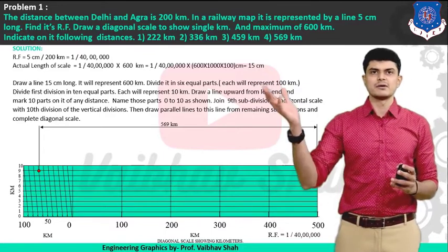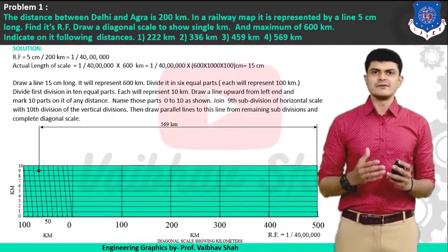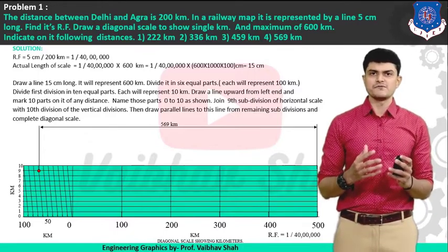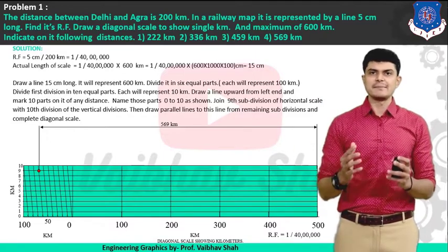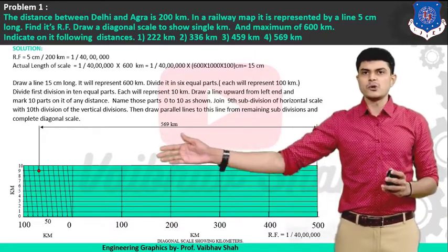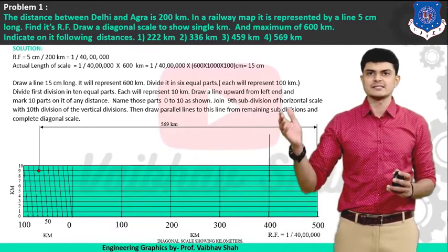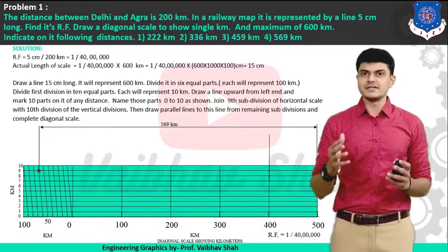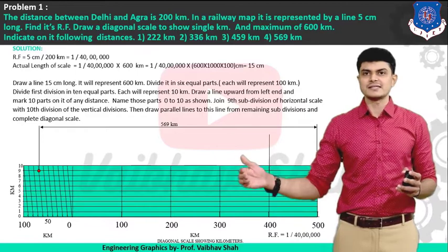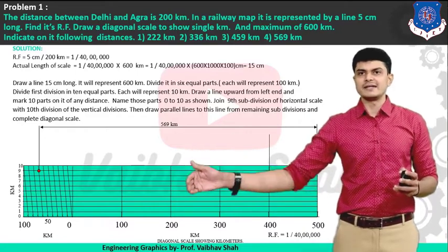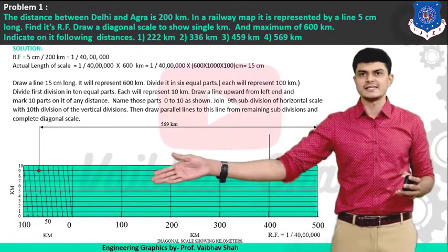So let us see one more example. We will be taking a third number first which is 459. So let us start dividing this number into 3 numbers first, 400, 50 and 9. So 400 we are using this primary scale. So let us start 0, 100, 200, 300 and 400. So let us draw one vertical line from 400 like this as I have drawn. After that we need to find out 59, that means we need to find out 50 on the secondary scale. So 0, 10, 20, 30, 40 and 50. As you can see on the secondary scale 50 is indicated there already.